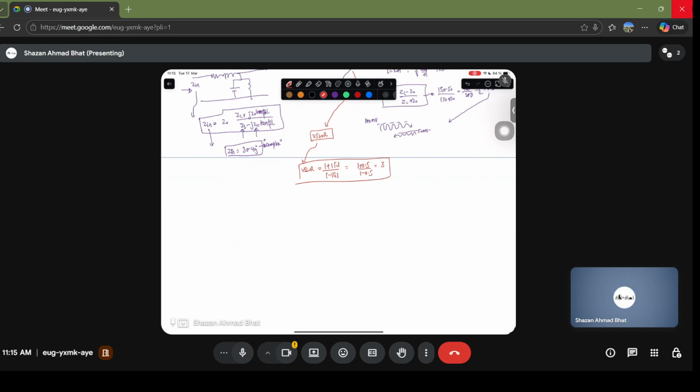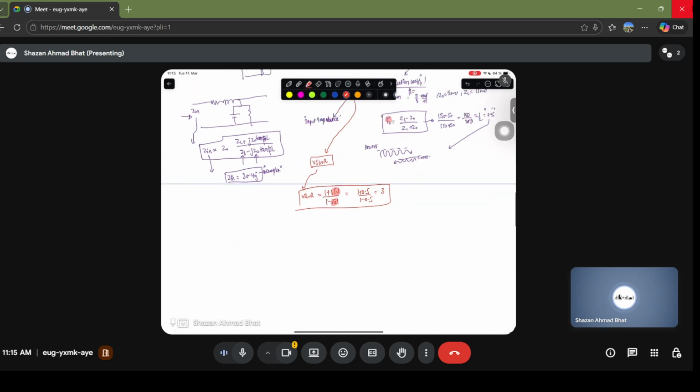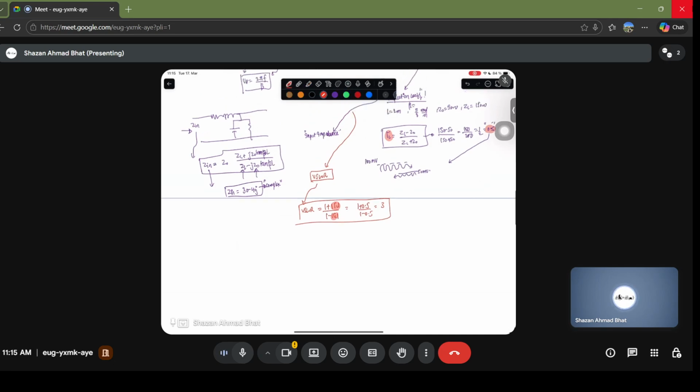Essentially, you need to take the magnitude here because this gamma L can also be negative. And that is really going to be important because the sign also tells you a lot of information about the phases of this electromagnetic wave. If you get a reflection coefficient of minus 0.5 instead of plus 0.5, it essentially means a phase change also.